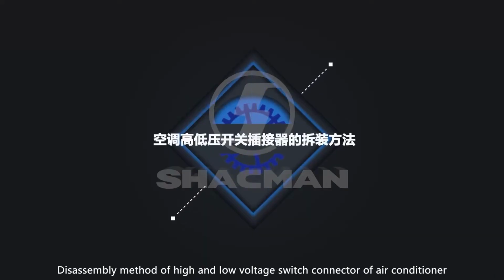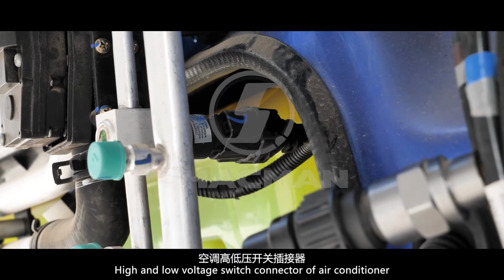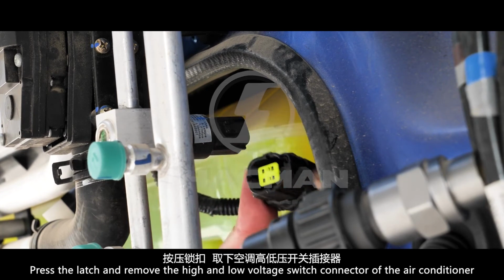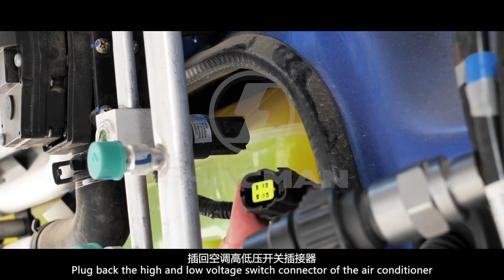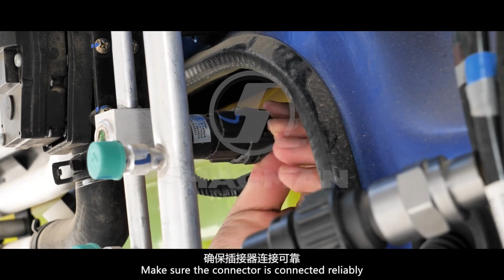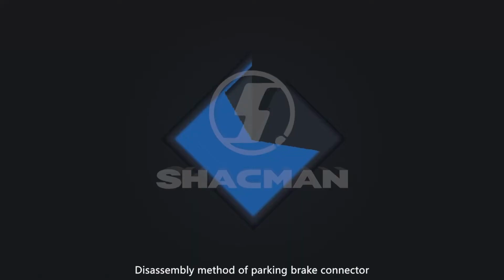Disassembly method of high and low voltage switch connector of air conditioner. High and low voltage switch connector of air conditioner. Press the latch and remove the high and low voltage switch connector of the air conditioner. Make sure the connector is connected reliably.